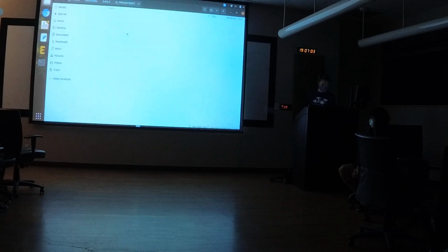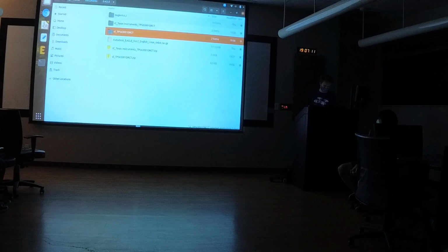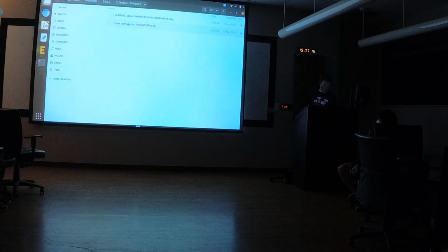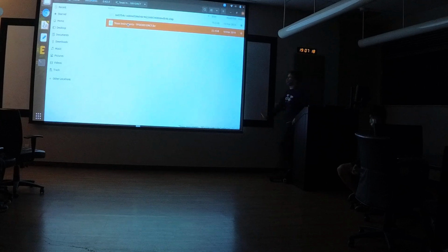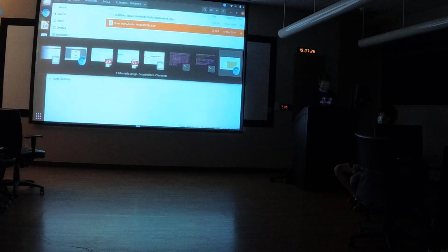If we open this, what we're going to find inside is... Okay, well, we're going to pretend we downloaded the one that I downloaded earlier, which I actually verified works. We're going to notice the .lbr file. The .lbr file is the library file that Eagle recognizes as the part. So now that we downloaded this correct one, what we're going to do is head over to,